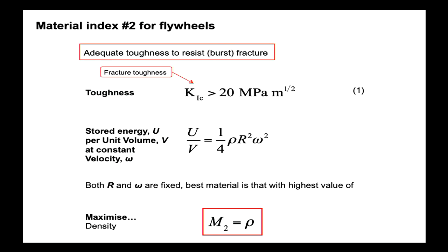The crack grows a bit more, grows a bit more, grows a bit more, and then finally we get shatter. The idea is to try and predict this crack growth so that we can plan for it. Aerospace pretty much designs to fracture toughness. Okay, so we've got a performance. As far as we're concerned, it's just another engineering property with a certain upper limit for fracture toughness.